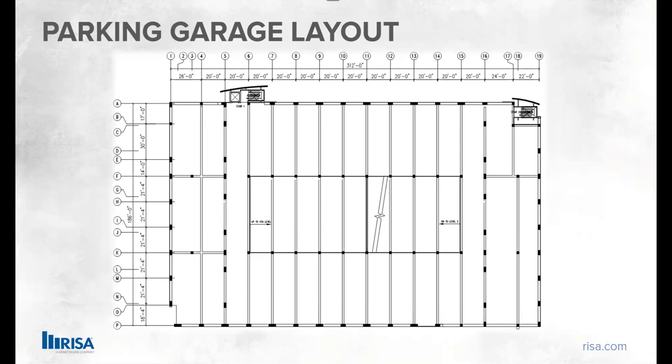So the first step is to split the slab up into X and Y strips. Usually the strips will be based off of the tributaries, but really they can be done in multiple ways depending on how you're going about designing your structure.